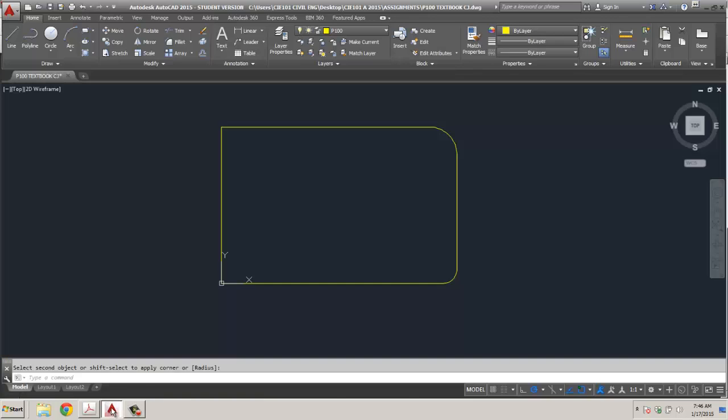Let's go back to our AutoCAD. Now, we have to place a circle. And that circle from 0, 0 is over 3 and up 2. How are we going to do that? Let's go to our circle tool. With your snap mode on, I want you to watch what happens when my cursor goes to this point. See how it snaps there? When I stop, it gives me an endpoint, and as I move my cursor to the left, see how it locks into that point?